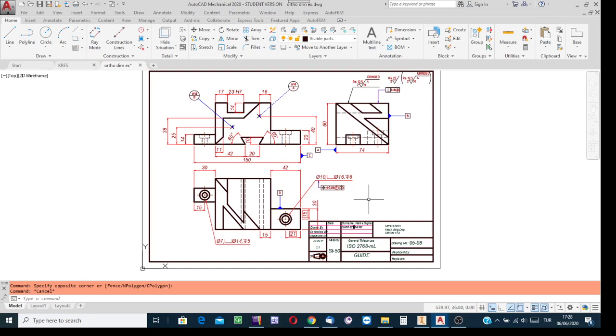The other engineering drawing in the classification is the assembly drawing. If the object is an assembly, then the page on which we find the views of the assembly and the overall dimensions and the identification numbers of the constituent components and the parts list, as attached to the title block, where the reader can find the names of the components, and along the notes column of the parts list, the reader can see the technical notes for the standard components. Yes, it is called assembly drawing.